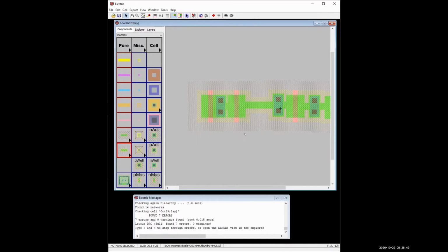Okay. So the errors that you're getting are because of the size of those notches effectively. Keep sliding that second transistor to the left. That's too close, because that big rectangle is the gate. A little bit more to the left, like 2 or 3 units. Stop there.